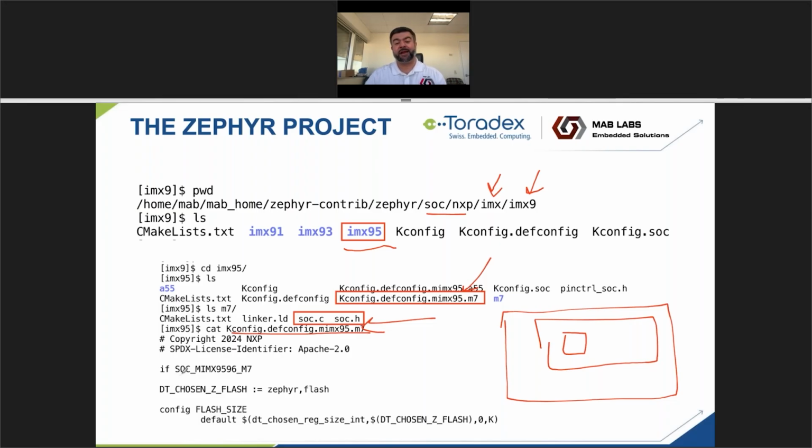That's not the case with Zephyr. Everything happens at compile time. So what ends up happening is the Zephyr build process converts the device tree into a header file, and then there are what are called bindings that convert the device tree into things that can be referenced in source code. And we can see part of that binding here, where the Kconfig specifies which node we're going to use in the device tree that corresponds to the flash system, and then eventually that's used by the software to do the appropriate initialization.